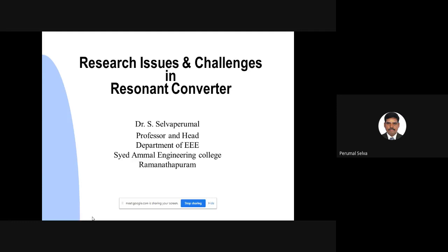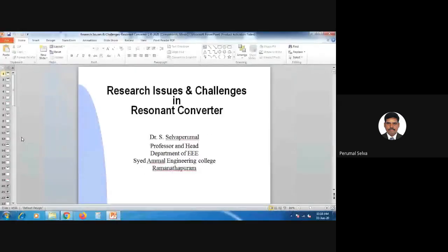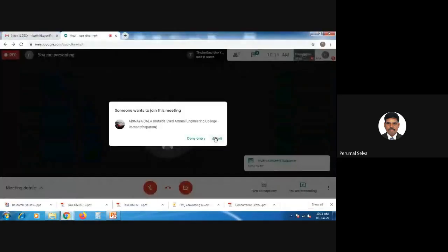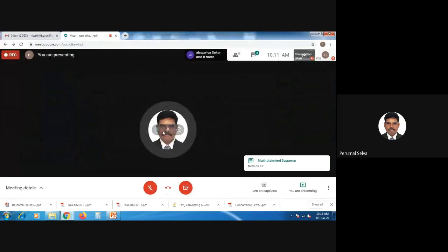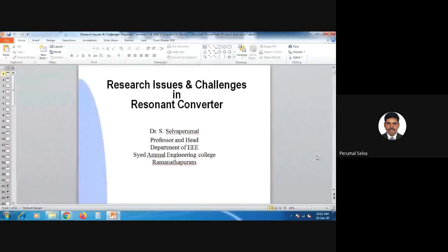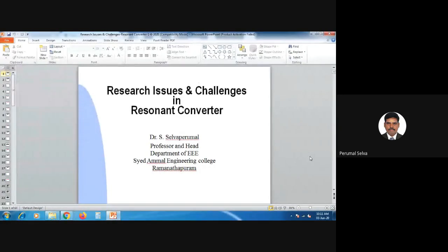The storage devices are inductors and capacitors. The process of energy transfer results in an output voltage that is related to the input voltage by the duty ratios of the switches. It is insightful and worthwhile to investigate why DC to DC converters are necessary before their detailed presentation and analysis. In addition to the constraints of size, weight, and cost, DC to DC converter technology also addresses the issues of efficiency and regulation.